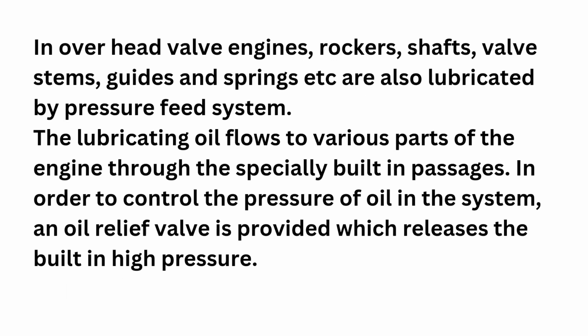In overhead valve engines, rockers, shafts, valve stems, guides and springs etc. are also lubricated by pressure feed system. The lubricating oil flows to various parts of the engine through the specially built-in passages. In order to control the pressure of oil in the system, an oil relief valve is provided which releases the built-in high pressure.